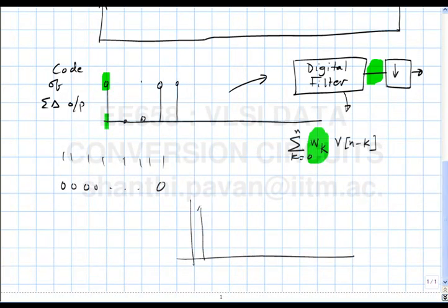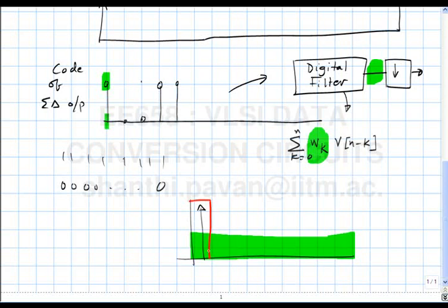So this is the signal, the sine wave, and if I just quantized it, this would be the quantization noise, correct? Now if I take a sharp filter and cut off everything beyond the signal bandwidth, what happens? The output spectrum looks like this. So I realize that this is now a vastly oversampled signal, right?